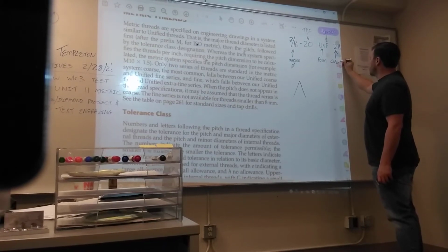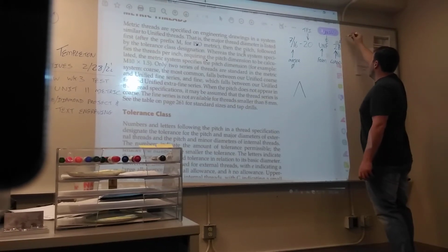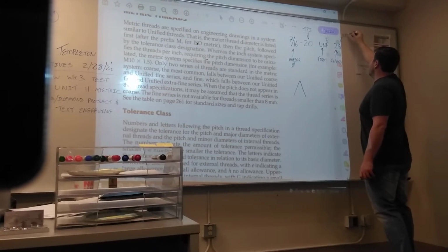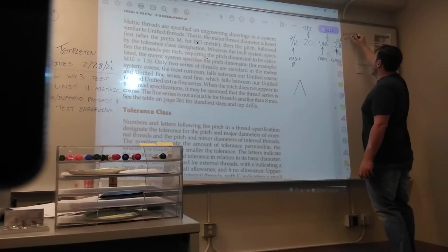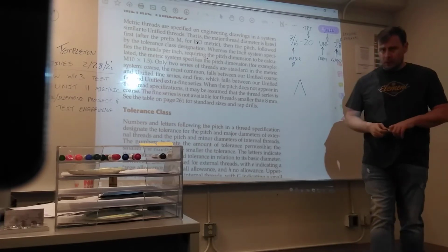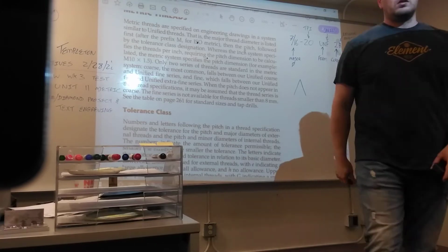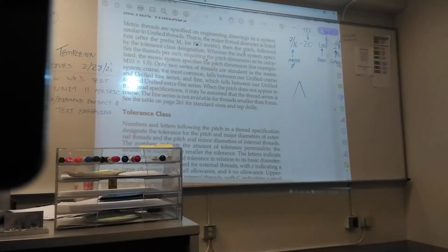The class is 1, 2, or 3, and the A or B is whether it's an external or an internal thread. Internal is B, external is A. So you were told to make a class 2 thread. How do you know it's class 2? There's only 3 classes, 1, 2, or 3.